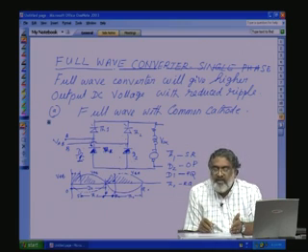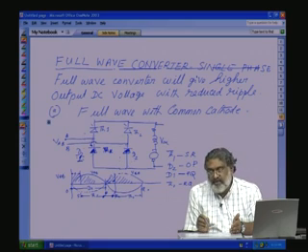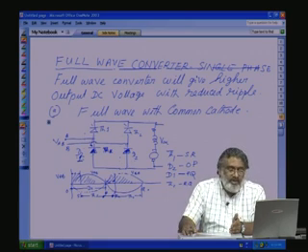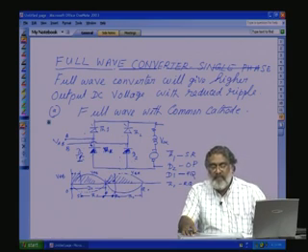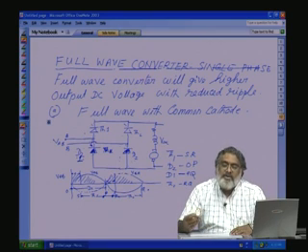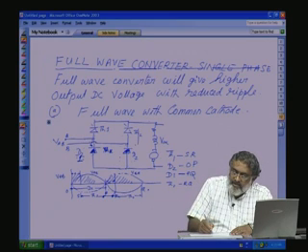But here, if the TH2 gate drive fails, we will fail to turn on TH1, and since the load is highly inductive, the load will freewheel through D1 and TH1. So how to avoid this? One way is to give a freewheeling diode. That means don't allow the load to freewheel through the thyristors. Let us go by the least resistance path by giving a diode across here.